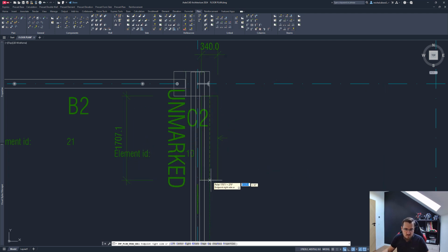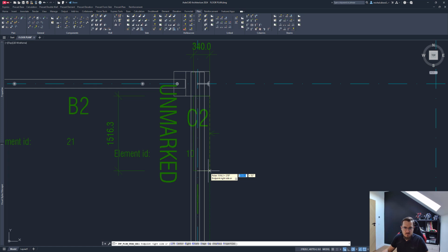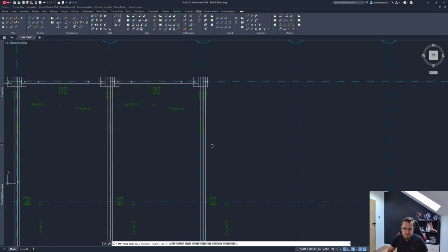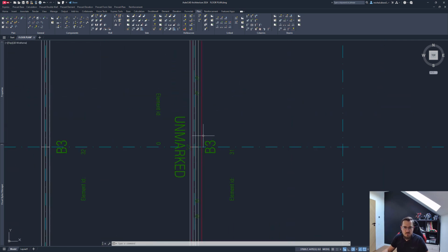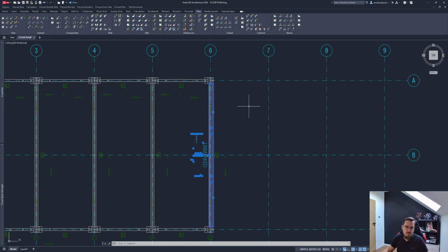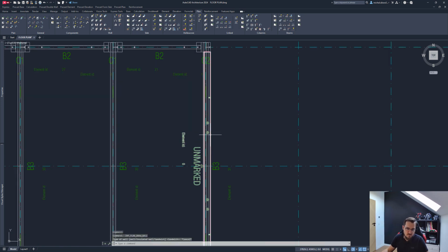I don't have to change anything since I'm going this direction, but what I want to change is the alignment of the wall. So I will just press L on the keyboard as per the tooltips on the bottom, and I'm good. I place the wall on the left side of the placement line. So I'm just going to click. You can immediately see, I'll press space for you, that the wall is marked red. That means it's too big. We have settings in Impact. They mention that if an element is too long or too heavy, it will give you such a warning, right? So the warning is red, so something's wrong.